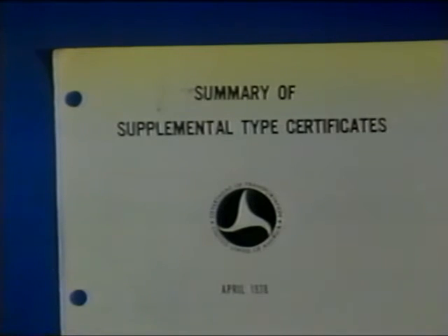The type certificate data sheet for the airplane will list the propellers that have been approved for installation on that particular aircraft. Propeller type certificate data sheets will often list some engine propeller combinations that have been approved by the propeller manufacturer. This information will be found in Note 9 of the data sheet. The summary of supplemental type certificates may list additional propellers that have been approved for a particular aircraft. These will be found under the listing for the aircraft's manufacturer and model number.